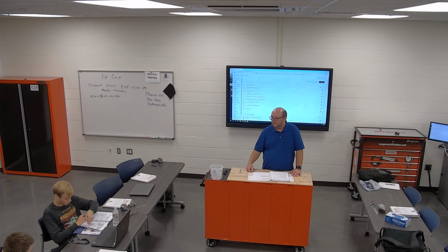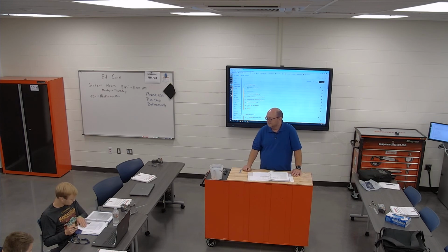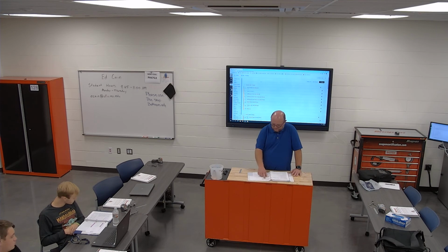I got a great book. All the way in the back, it's like the last 3 pages. There you go. So, your shell mill's carbide. So that would be 800. If you look at the carbide, you get 800. Follow it, John? So then you take your 800 times 4 divided by the size of the cutter.